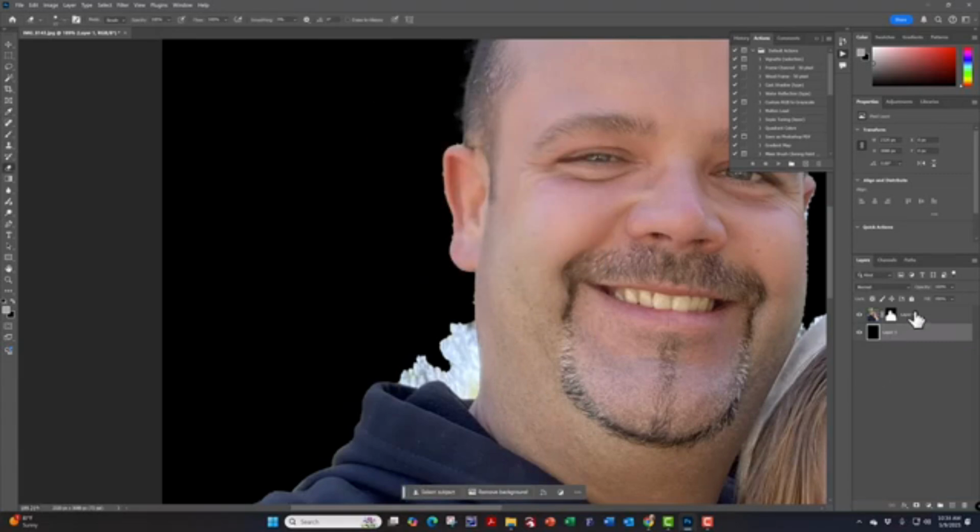Mine is already set to black, so you want to do that. Now you want to make sure you have the image layer selected and not the background, so I'm going to do that. Then I'm going to come here and I'm going to start to erase. And you can see that if I drag the cursor over this, I start to erase it. Okay, and what I like to do is erase along the edge first, so that if I have any issues, I can correct those. So I'm just going to erase along the edge. I'm just slowly moving here, and if I'm not 100% perfect, again, it's not going to matter that much, because these are the edges that are going to be warped to the back.